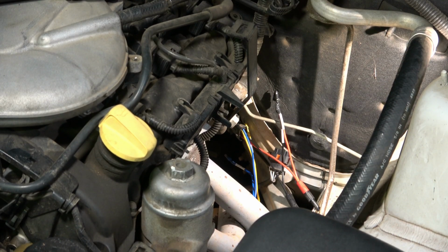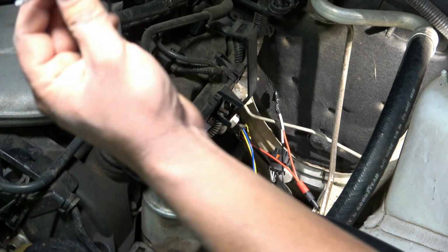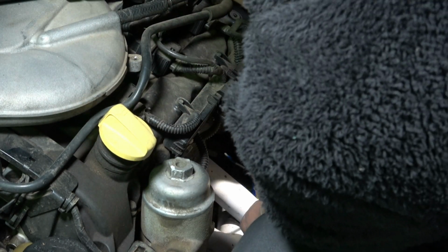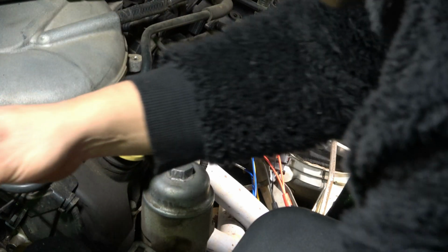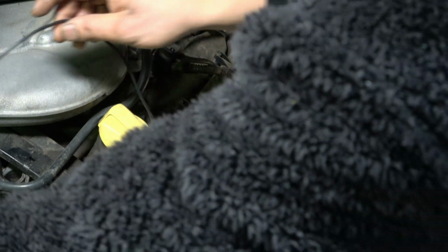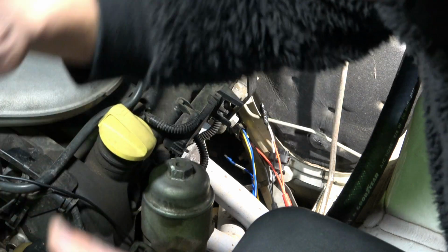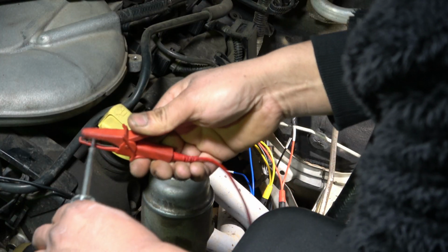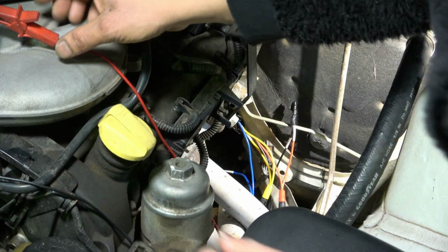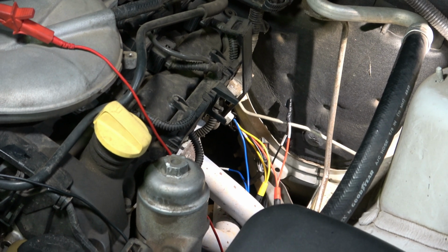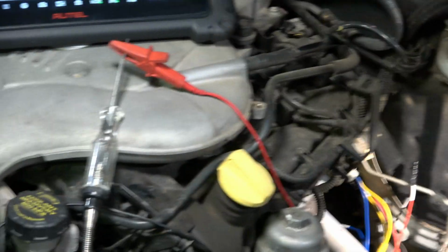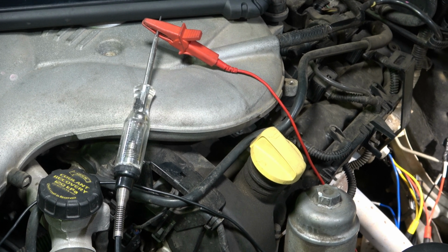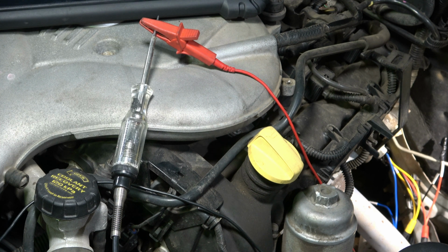I'm going to use a test light, so I'm going to connect the extension lead, one on the black, and I'm going to go black onto one side of the test light, and connect this red extension to the red extension we made there, because if everything is good, this test light should light up, but it's not lighting up. This test light should light up if everything is done right, but it's not. So I may cycle the key or try to start the car and see if that heater circuit turns on.